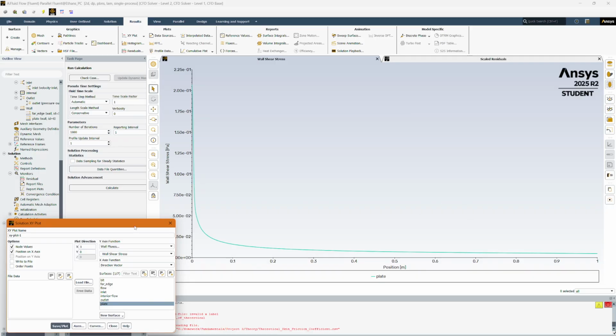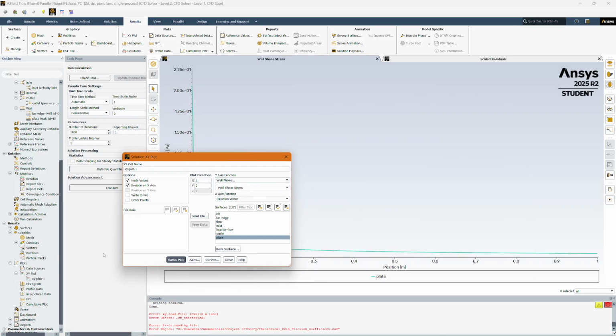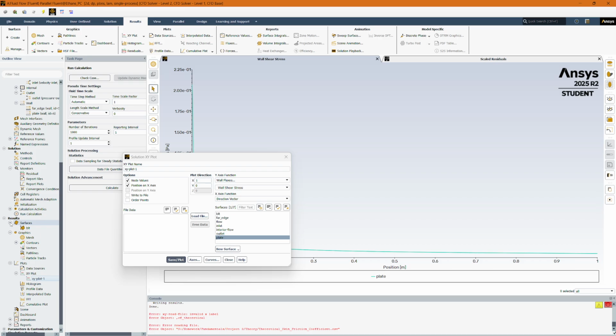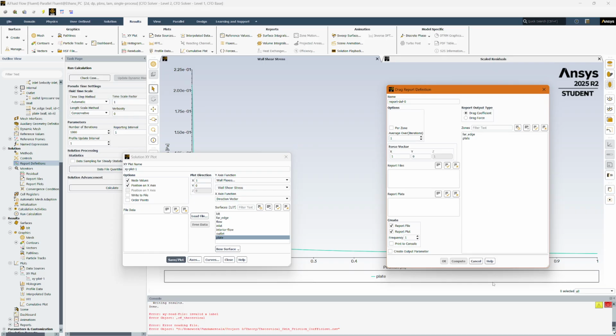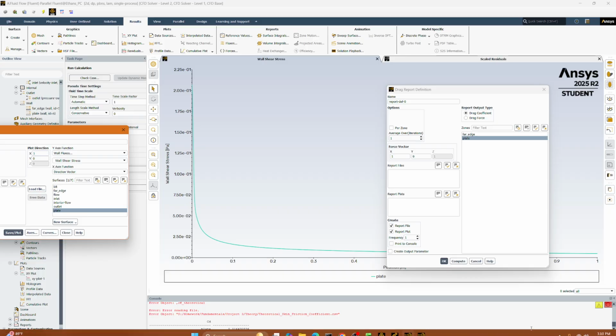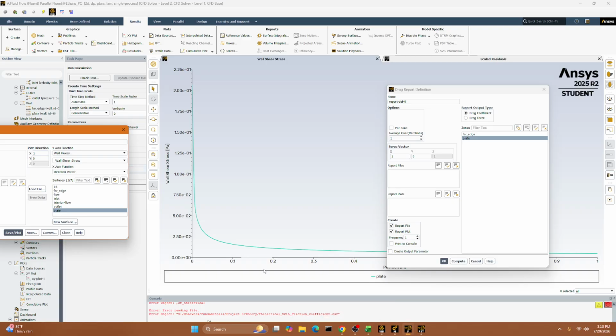To get my drag coefficient, I'm going to come down to, where is it? Surfaces? Nope. That's not what I want. Definition? No. Force support, drag. Drag coefficient. Compute. Far edge. No, plate. Compute. There we go. CD is 0.016430086. All right. So that's everything you asked for. I will compare theory and actual in my report once I figure out how to convert everything.